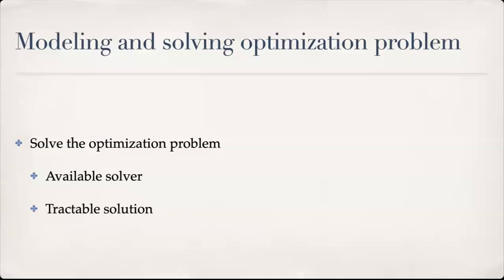Also, in some cases, for example, optimal control problem. As I mentioned to you, we can use optimization as a controller, okay? You solve the optimization problem and you have to implement those manipulated variables you obtain from the optimization problem. You know, the controller has to implement every 1 minute or 2 minutes, or even shorter than that, okay?